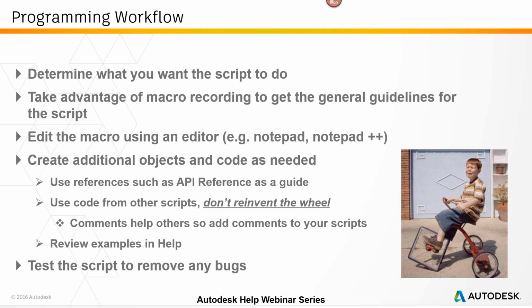Use macro recording to get started off. Again, it's not perfect because it is very specific, but at least it will give you a bulk of the script that you want to do, and then you can do some modifications by using Notepad or maybe the VBS Edit.